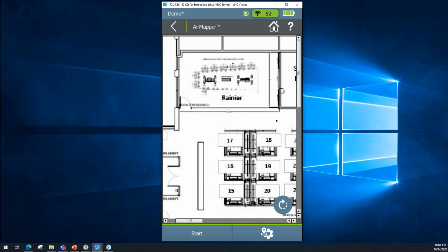So the way the process works, just tap on start here in the lower left. Let's say I want to start on this corner of the building, or this conference room here. So I tap there. Notice that my signal propagation for this example still seems a little too big, so I may want to cut that down. If you see this happen, that's a problem, because I have to walk here, and I'm still in the circle, but I have to change directions, so I should tap again. If you see this, that's a bad practice.